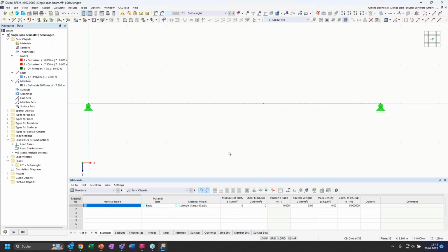That can be helpful later when you have to design such members. You can still design this member as one continuous member, and you don't have to define two members or set up the options for the design of two members. Okay, now we also have our intermediate node.